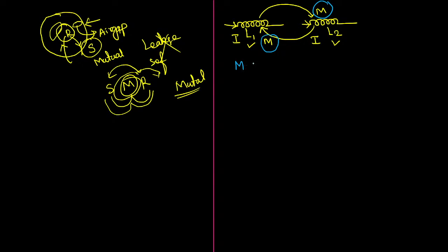Let me call it like this. First, 1 to 2: the mutual inductance offered by the primary coil in the secondary coil. Because of the primary coil, some mutual inductance is developed here. It will be equal to the mutual inductance developed in the primary coil due to the secondary coil. So M12 means interlinking from 1 to 2, and M21 means interlinking from 2 to 1. This will always be equal. We can keep the same value.